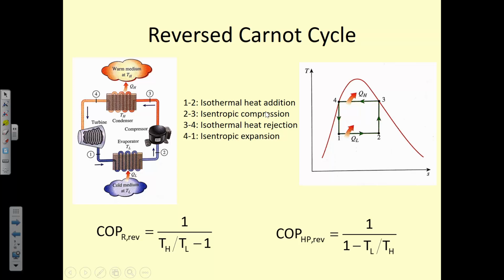Okay, we know about the Carnot cycle. We've talked about it a lot in this class. It's the most perfect, ideal, reversible cycle. Its diagram is a little square on a TS diagram, so we like it. It's easy to analyze. It consists of 4 processes. 2 of them are isothermal and 2 of them are isentropic.